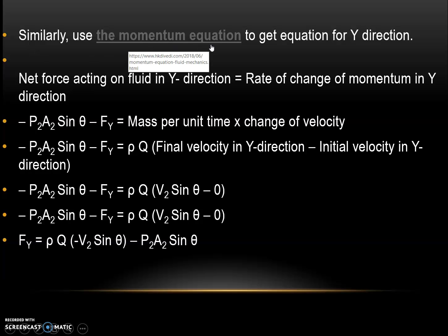Similarly, we will use the momentum equation to get the equation for the y direction. The net force acting on the fluid in the y direction is equal to the rate of change of momentum in the y direction. So, minus P2A2 sin theta minus Fy is equal to mass per unit time into change of velocity, that is rho Q into the final velocity in the y direction minus the initial velocity in the y direction.